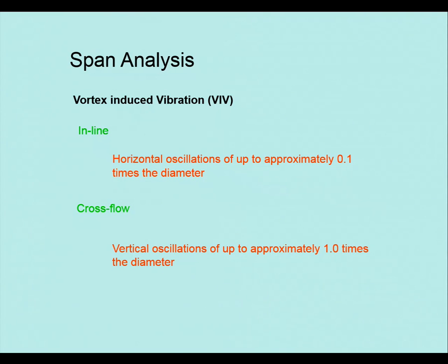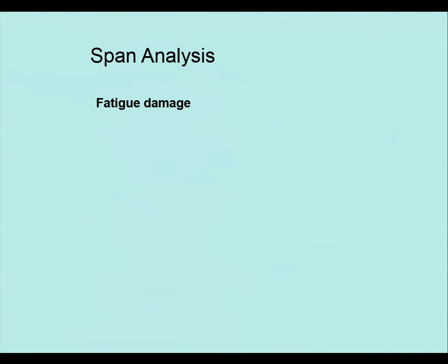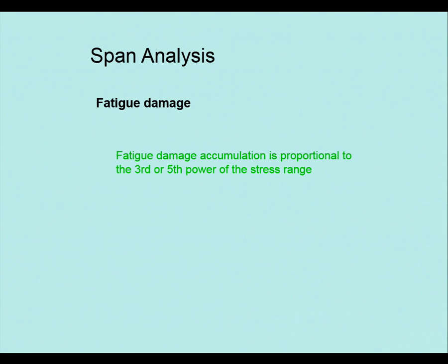Now this is when, if you've got a spanning pipeline, your fatigue and the stress cycling has to be looked at very, very carefully. So it isn't just what you've got on the pipe sitting on the seabed, it's what's going to happen to it. And you get fatigue damage.